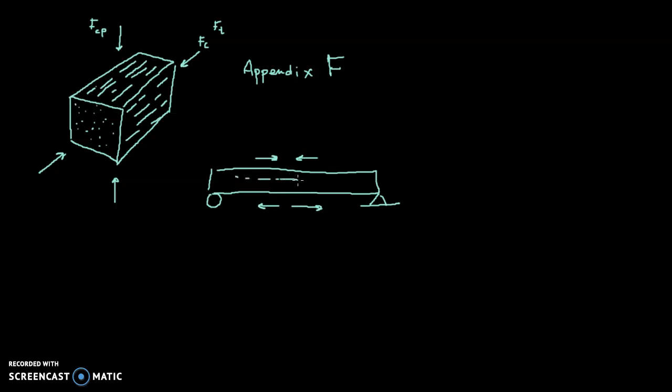And those two forces, the tension and the compression, are parallel to the wood grains. Wood is laid down on its side when it's used as a beam, and so that grain runs left to right. And both of these directions are also running left to right. So wood is strong against bending because the stresses are parallel to its grain, not perpendicular.